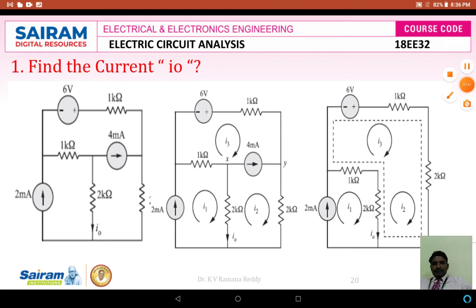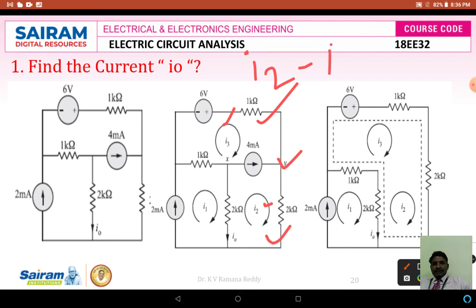Now, applying the super mesh analysis here, a 4 milliamperes source is there between the boundaries of loop 3 and loop 2. According to the currents I already assumed, I3 and I2, the I2 current direction is along the 4 milliamperes, so I want to give the priority to I2. I want to write the difference of these two mesh currents, that is I2 minus I3 is equal to 4 milliamperes. This is our first equation. Already we got I1 is equal to 2 milliamperes.